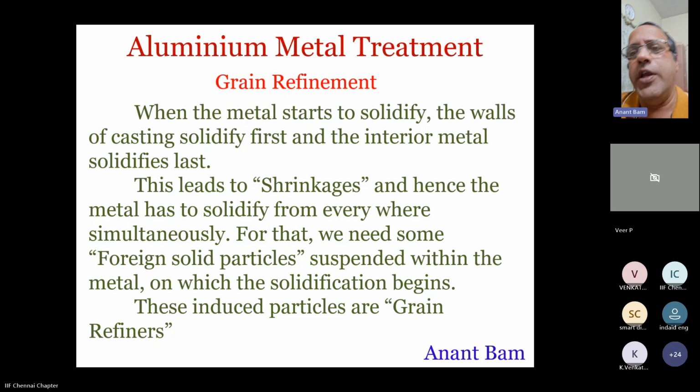In case of aluminium, depending on the grade, it may vary from 1.6% up to 4%. But normally, if we take it around 2%, then naturally there is a gap of volume between liquid and solid by 2%. The liquid will occupy 2% more space than the same weight of solid.